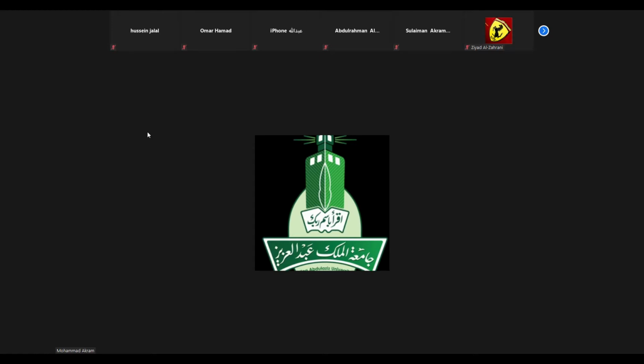Yes, the question wanted Z1. How much is Z1? You check the difference. Z1, because the slope is given, 1 in 30. Based on 1 in 30, it means in 90 meters it will be 3 meters, right? So it will be slightly more than 3 meters. It will be 3.33 meters. Yes, that's right.